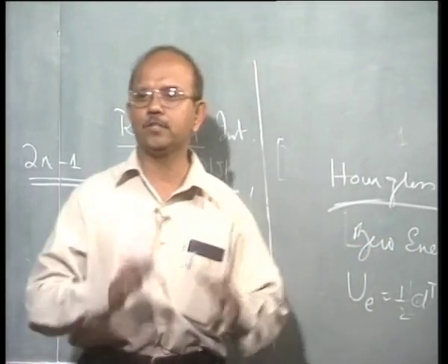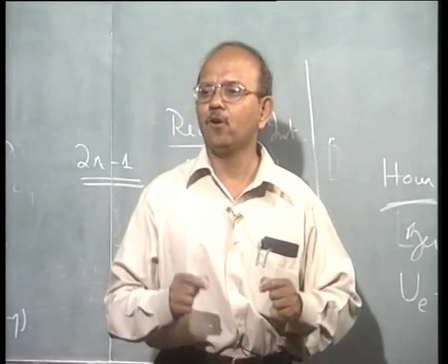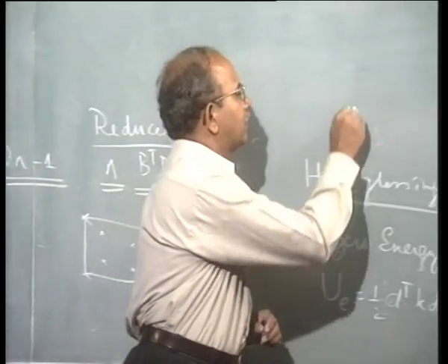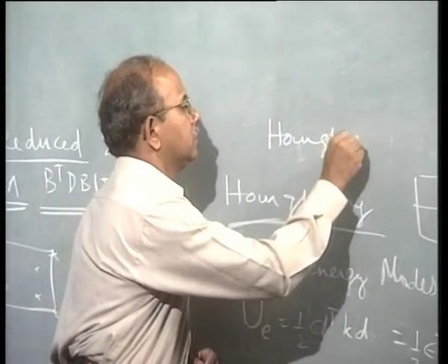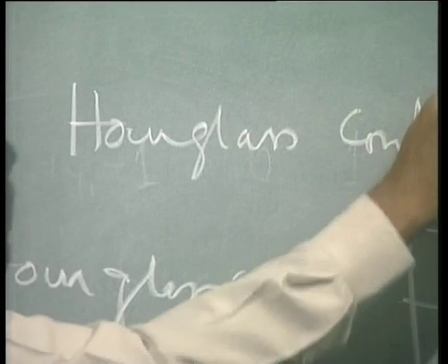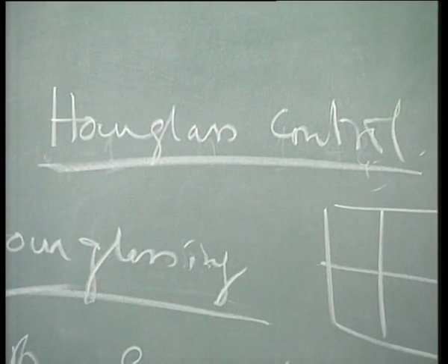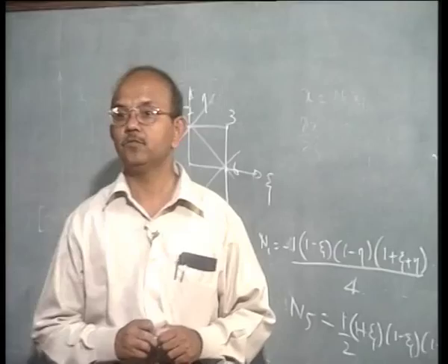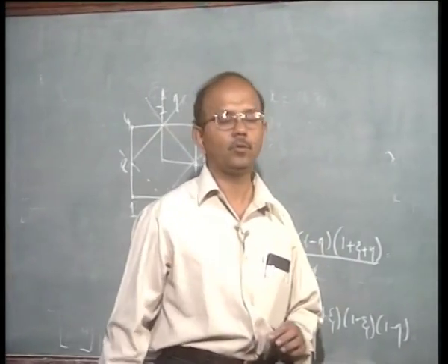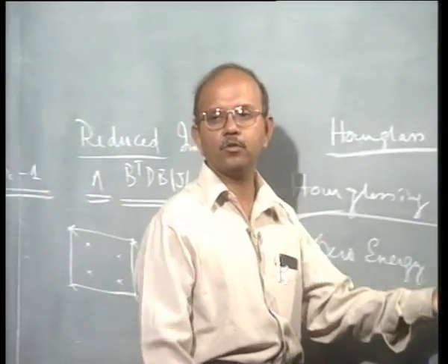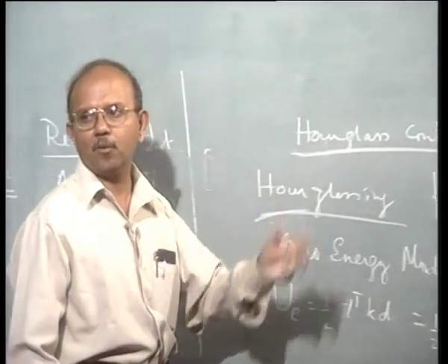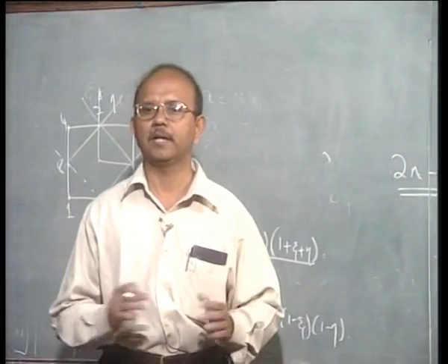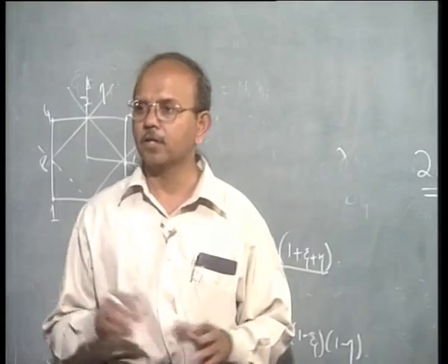So they do reduced integration, but they also do a repair job by doing what is called hourglass control. They have another algorithm which also controls these hourglass modes. But of course, hourglass control does not work all the time, because of certain limitations.